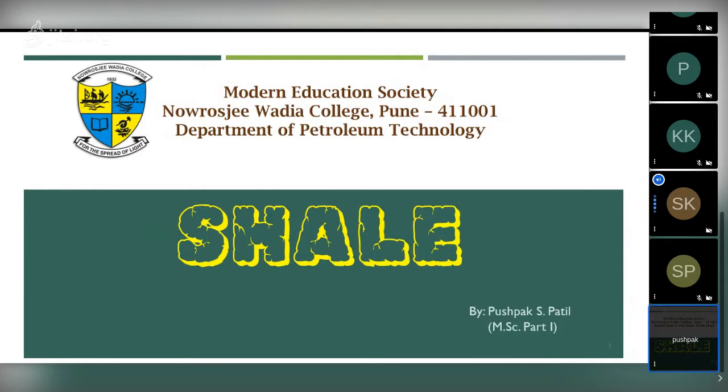BHA pickup is bottom hole assembly. We are taking it part by part and assembling it on the rig floor. So we first take the bit. Then, if you want to drill with a mud motor, we take a mud motor, which is used to give direction to the well. And RSS is the rotary steerable system. After that, we pick up the other components of the BHA modules.